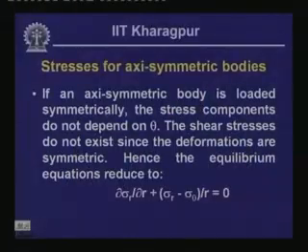So, the stresses are independent of theta, and these kinds of bodies are called axisymmetric bodies. That means these bodies are perfectly symmetrical with reference to the vertical axis. And for such bodies, if the loading also is vertical and symmetrical, then at any cross section we take, at each section the same state of stress exists, and this kind of stress system and bodies we call axisymmetric.